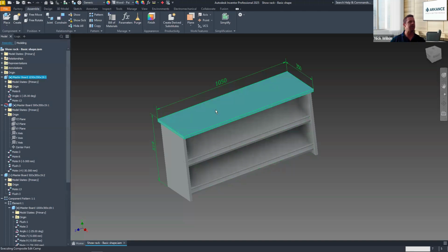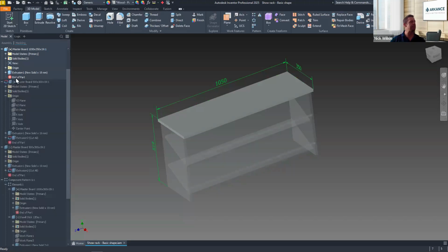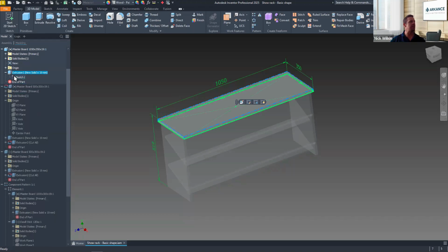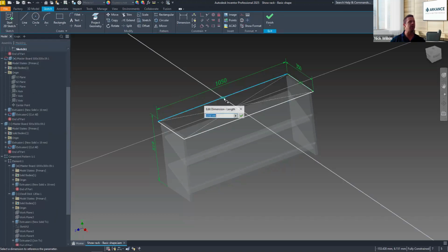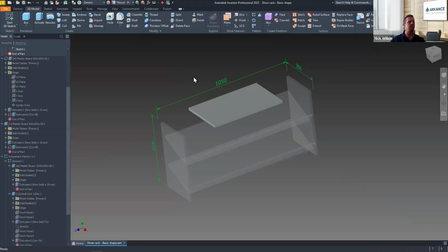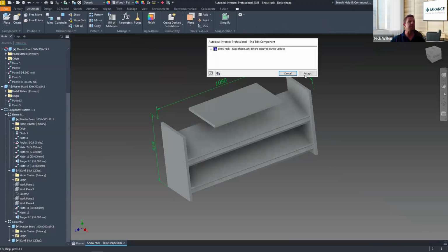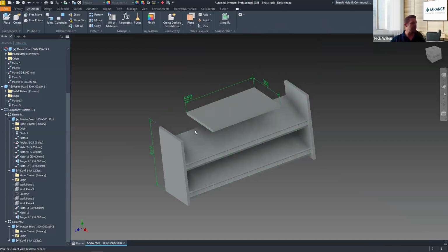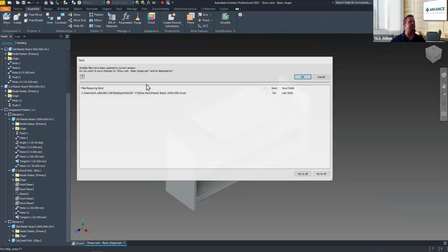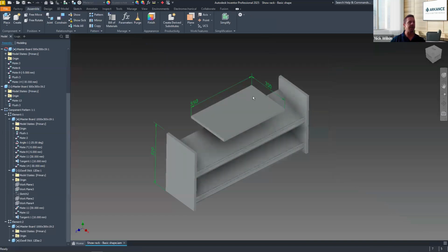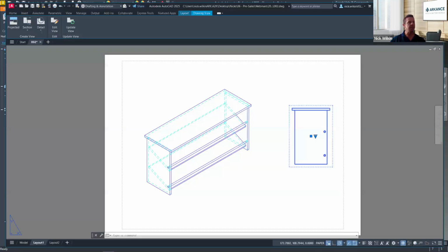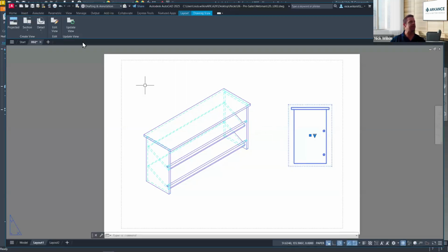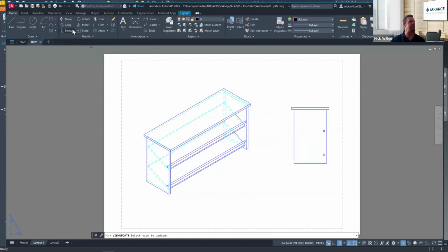There it is. I'm going to access this file here. I'm going to change the size of this board at the top, very easily, by 50, for example, half the size. It's totally off, but that's what I want to see. I want to see that change. Now, even though I save it, it should update in AutoCAD, right? This is something you would imagine actually updates. You even have a button over here that says update view. So I can select all these views and go update view.